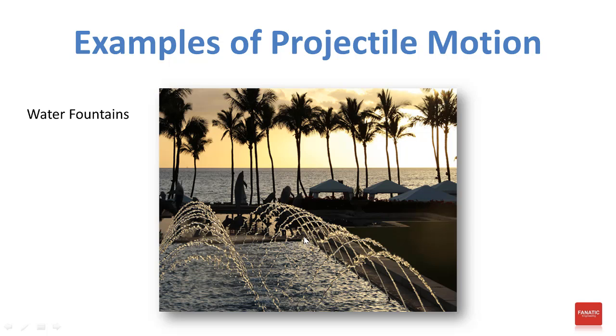We will automatically get this pattern, which will be the same as we have designed for the first one. But we should have the same values of the velocity and the same value of angle of projection throughout the injectors. So we will get this. If the angle of projection for the first one is 30, and for the second one is 35 or 32 or 33, something like this, we will not be able to achieve the same pattern or the same path for the second injector as we have designed for the first one.